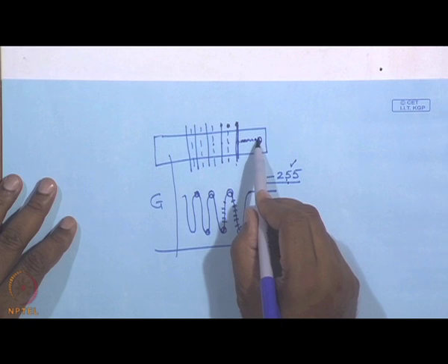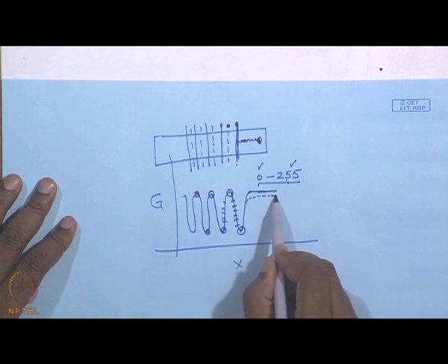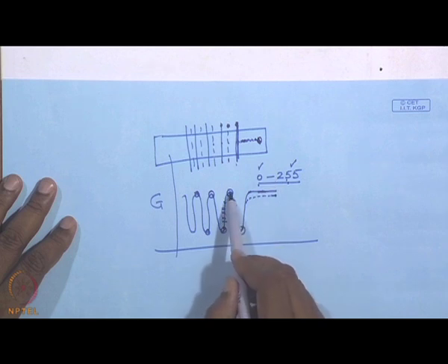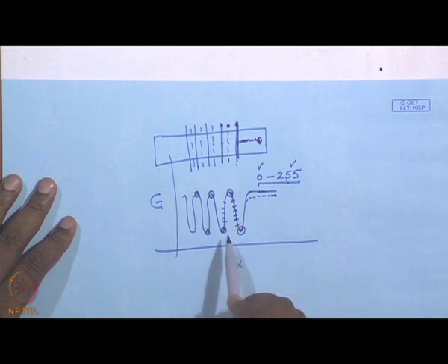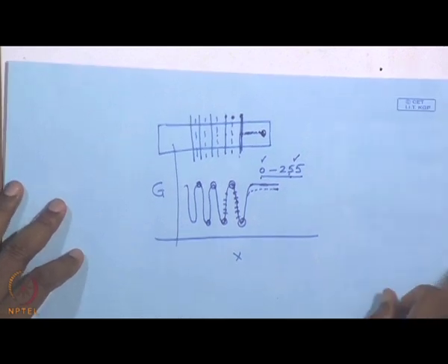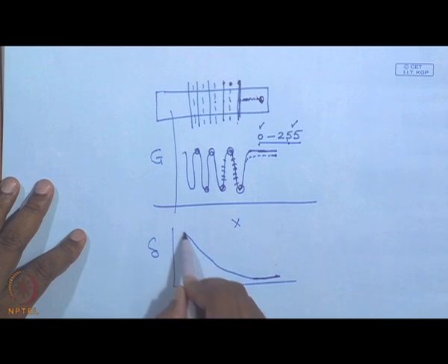If the adsorbed film thickness is more, then it is going to start from here. The reflectivity of the film covered surface will be even less. So, finding the gray values of every pixel, that means finding the reflectivity of every point, it is now possible to convert the pixel data into film thickness data. So, delta versus x starts at a value which is the adsorbed thin film thickness and increases till it reaches the capillary part of the meniscus.